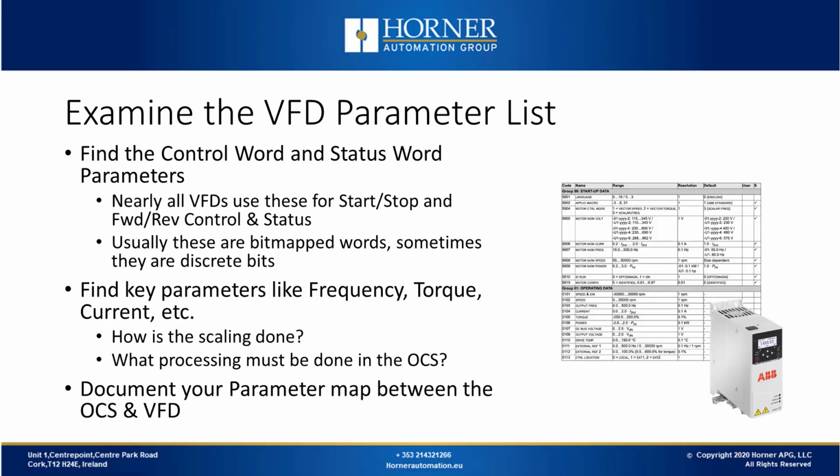The next step is to look at the VFD manual and find the parameter list, because there are some parameters you're going to need to find to successfully interface with the drive. It's going to have a whole host of parameters that are accessible, and usually a bulk of them are accessible over the network. You're going to want to be familiar with which parameters you care about for the application, and which parameters you may want to occasionally access, maybe from an operator interface screen, as opposed to parameters that you want to monitor and or change on a real-time basis.